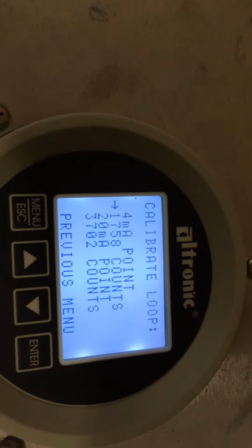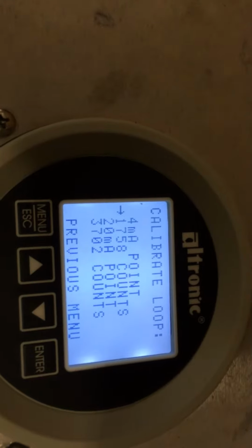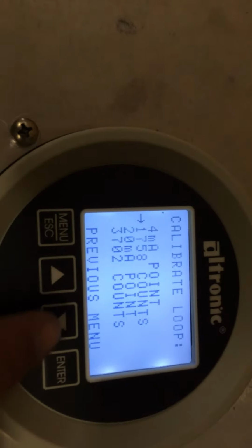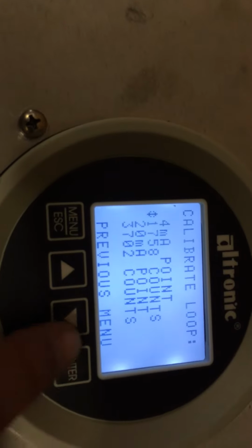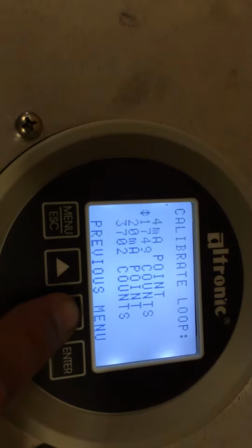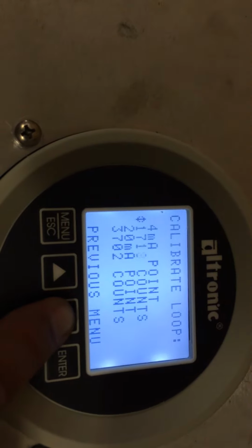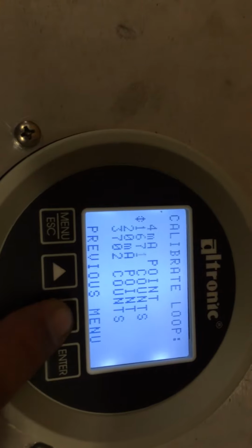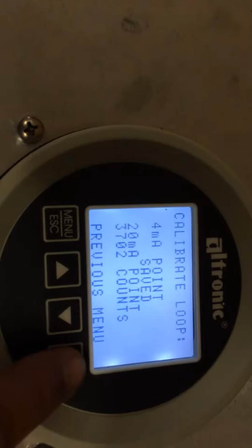Let's say the desired RPM stops dropping around 1050 RPM. Hey, I'm good there. Now I can leave it in auto, but I want to tweak it and fine tune it. Maybe I want to drop it down a little bit. So now I just sit there and hold this while I watch my desired and actual RPM. I get the value right where I want it, and I push save and I'm done.